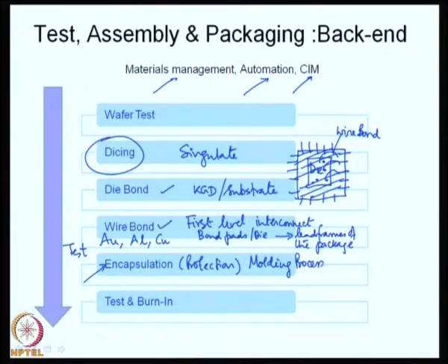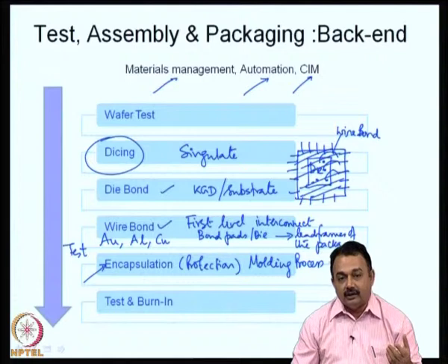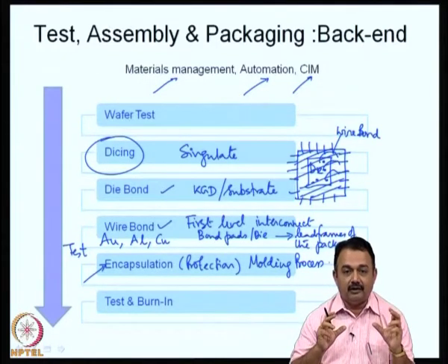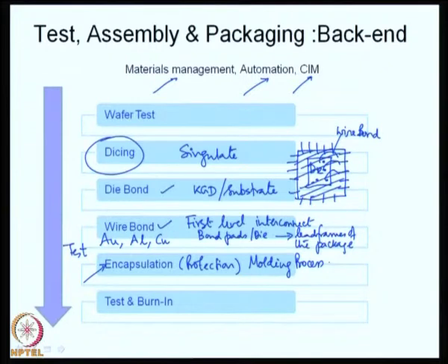The wire bonds are now protected, and then the lead frames come out from this die and connect to the external world. Now, this particular component will go to a printed wiring board or a printed circuit board, and then the second level interconnections will take place. The second level interconnections are basically your solder connections. So, I hope you get a clear understanding about what is a first level interconnect and what is a second level interconnect.